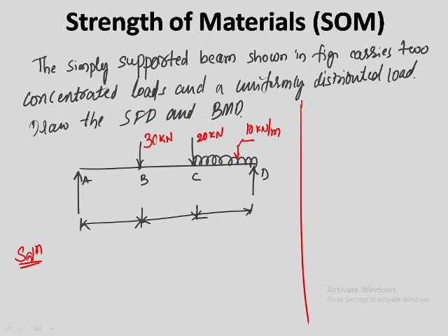You need to find out first the reaction forces. So can you calculate what is the reaction force at A and B? Once you get the reaction forces, then you can easily calculate all other parameters.